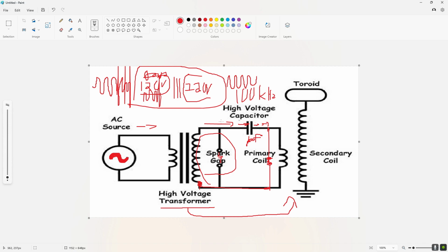usually high current. Because what's the typical current of an outlet in your house? It's going to be 15 to 20 amps. 15 to 20 amps of electricity is a lot of electricity. Okay, so you have to have thick wires. When you have to have thick wires, that means the coils on your transformer have to be thick enough to carry that much current, and that means it has to be large. Okay, so isolation transformers are usually expensive because they take a lot of material because of the size of them, and they're usually very large and heavy, very heavy.